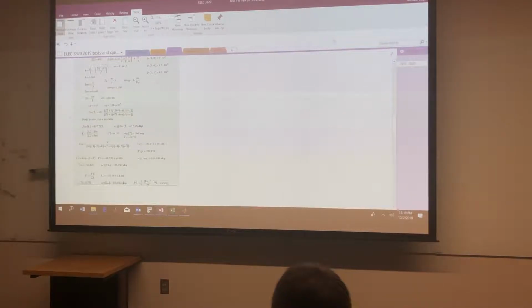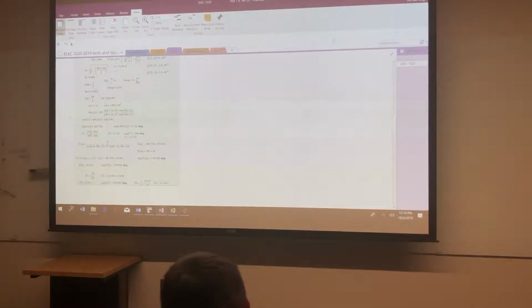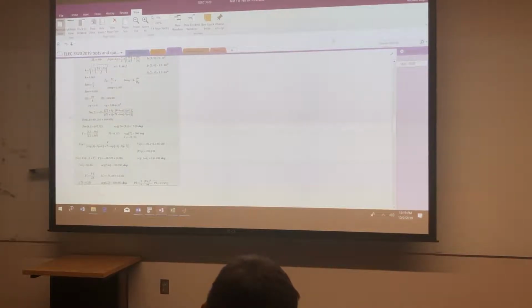Oh, you've got to get the reflection coefficient, ZL minus Z naught over ZL plus Z naught. Now that Z naught is the characteristic waveguide impedance. It's not the impedance of free space. Follow me, class? So that would be the Z naught we calculated for the TE10 mode. Everybody hear me on that? Don't make that mistake again. You'll see this kind of problem again. All right, now that said, so now we can get the input impedance and all that.